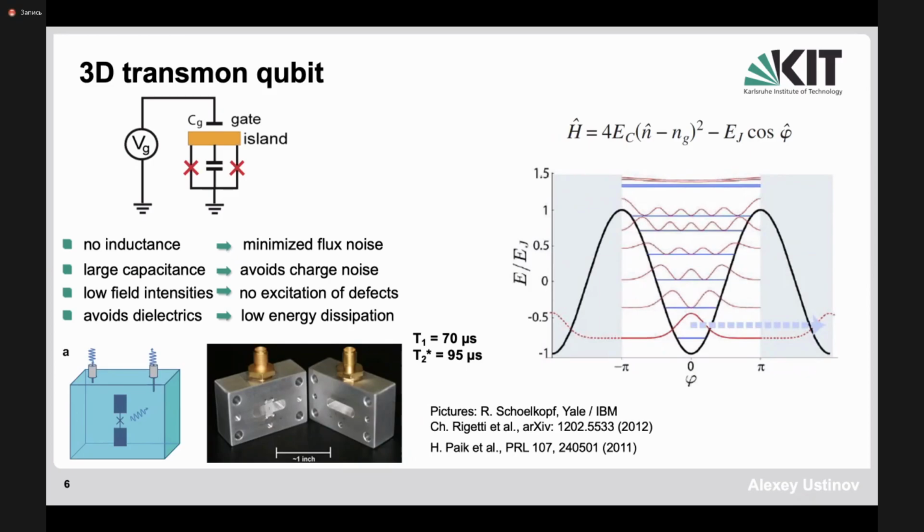So basically, having the qubit, which is a single Josephson junction, it's not practical to use a SQUID here, because the qubit is surrounded by a superconducting box. You cannot really apply a magnetic field inside a superconducting box. Therefore, people mostly use fixed frequency transmons here: just one Josephson junction and 2 large electrodes of the size of about a millimeter give the right capacitance to operate this at a frequency, let's say, between 4 and 8 gigahertz. So this device has no inductance.